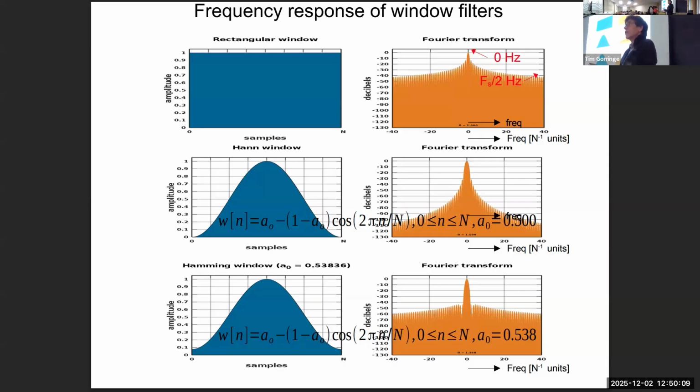If you remember back to the Fourier transform, the Fourier transform of your real signal in the time domain is a complex quantity in the frequency domain, and it is actually mirrored on the left and right of the low frequency, the 0 Hertz point. And so here's 0 Hertz right at the center of each of these three plots.